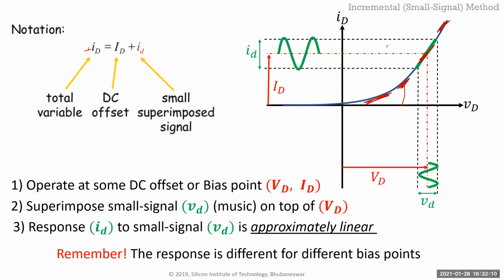And then the lowercase signal name with a lowercase subscript, that's only the variation. And in small signal, that is all we are calculating. So when I said delta V out over delta V in, I was basically calculating small v out by small v in. The DC bias, I'm just saying that's constant. I don't need to worry about it. The signal or the model doesn't perturb much, so that's why.